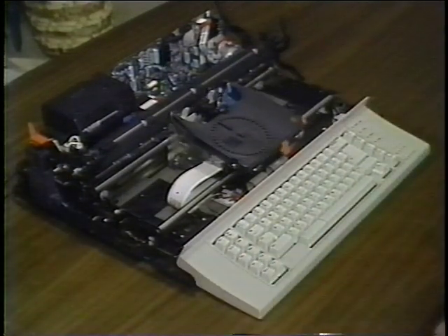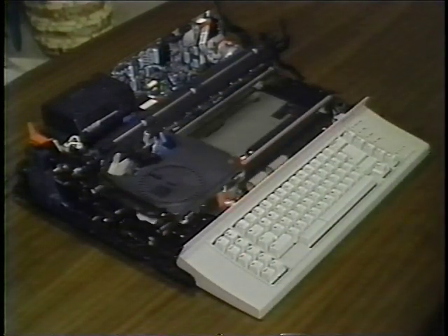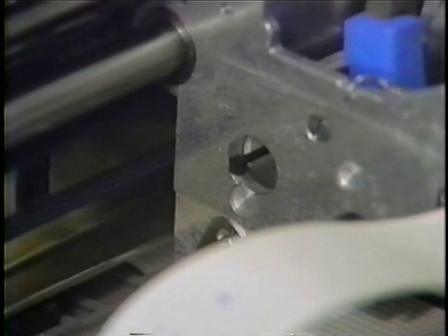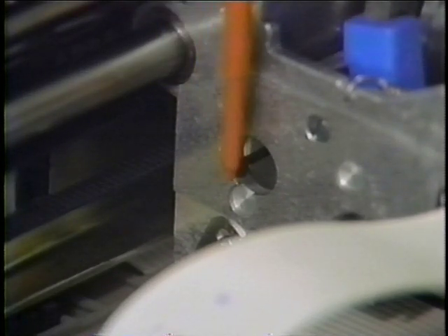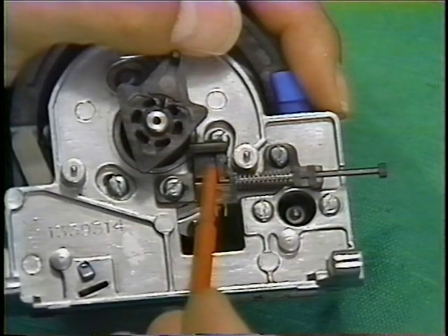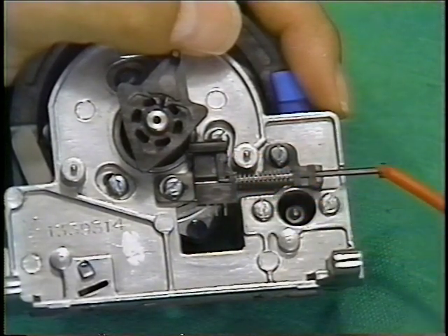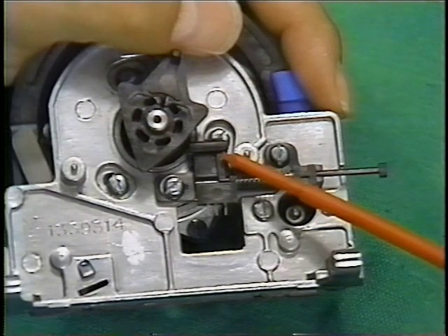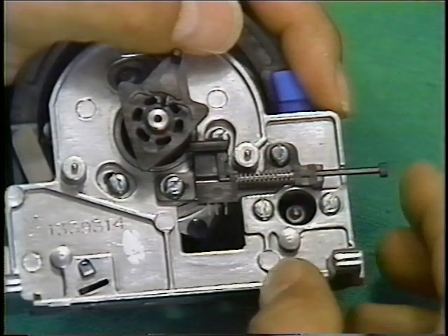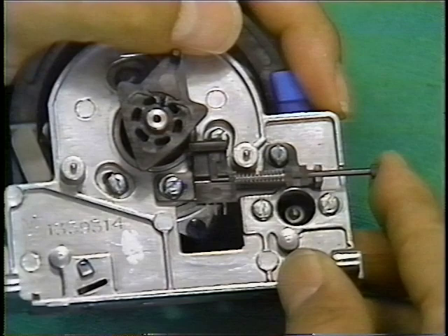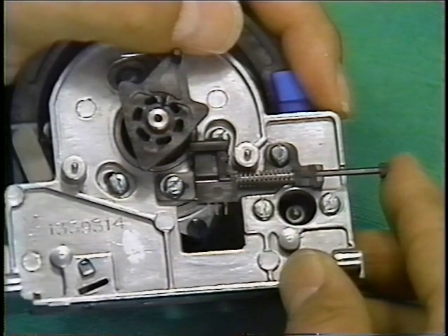During POR, the transport motor moves the carrier to the left side frame, then back out to the left margin. The homing flag tells the printer board when the carrier reaches the left side frame. Let's see how this is done. When the carrier reaches the left side frame, the end of the flag hits the homing flag stop and causes the flag to move into the carrier. When the flag moves in, it passes in front of the homing sensor, blocking the light from the LED, telling the printer board the carrier is at the left side frame.